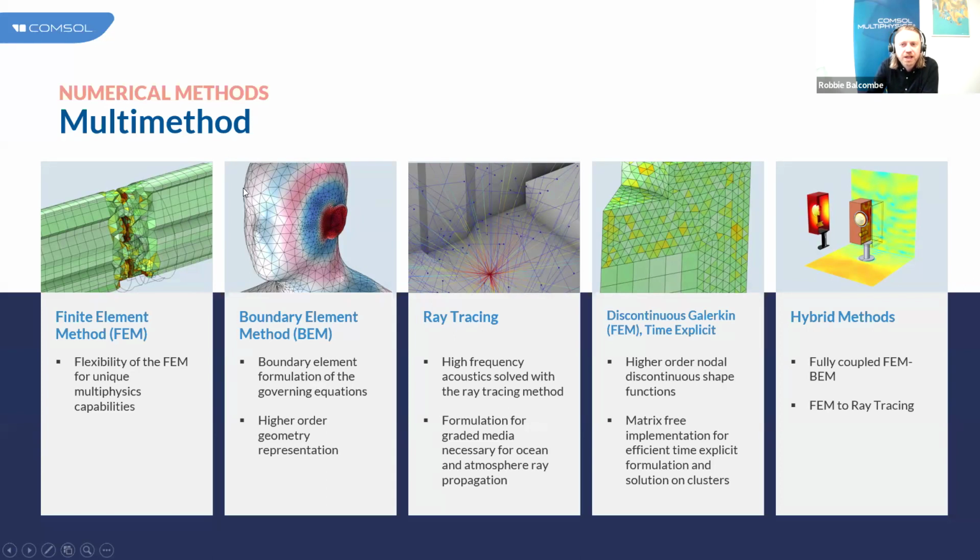When we work with the boundary element method, what we will actually set up is a surface mesh on the surfaces of our geometry, where we have reflections and we have surfaces which are radiating, and we will actually compute the solution based on this surface mesh. When working with the boundary element method, we can actually still recover the solution throughout the volume, even though we compute the solution only on the surfaces, because we can actually extrapolate the data within the volume, even though we've used just a surface mesh and computed a surface-based solution.